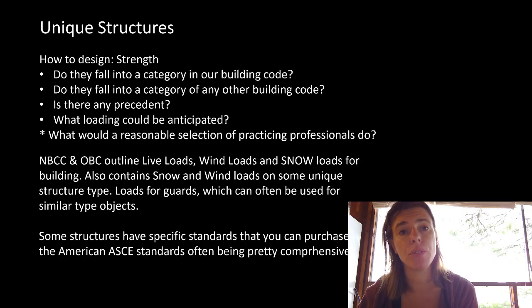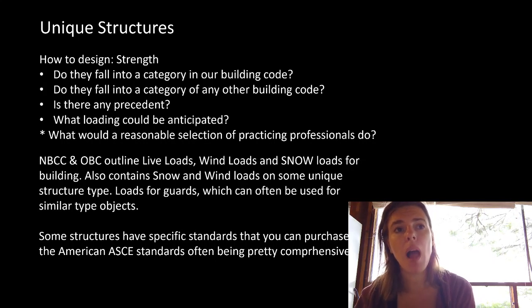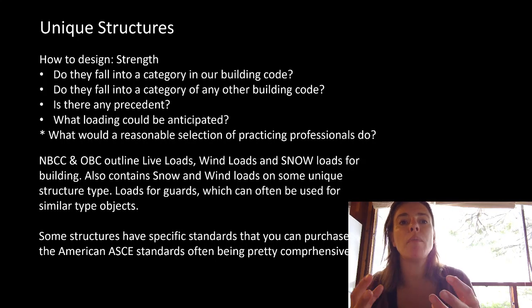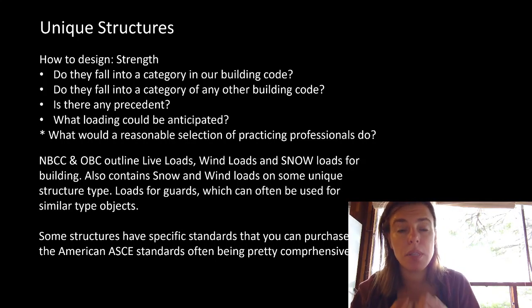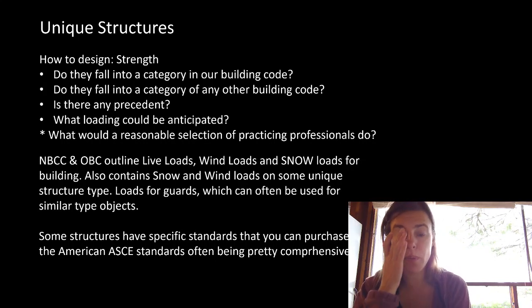So for art structures, for example, I could imagine somebody leaning on it or hanging off of it, and I use the same loading criteria that I would for a guard then, because that's what one person can physically induce on the system. It's not all the people trying to fail something at once like a floor would be.